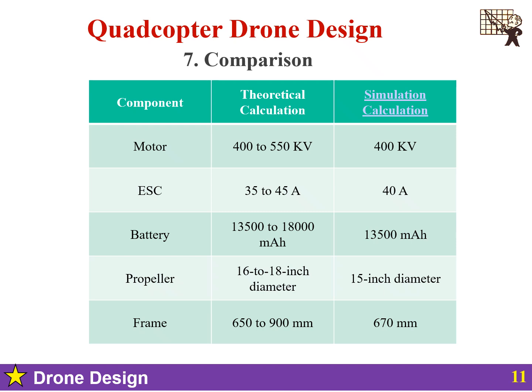ESC ratings. It lies between the range of 35 to 45 amperes in the theoretical calculations, while in simulation we get around 40 amperes. The simulation chooses the mid-range, balancing the cost with thermal margin. This represents professional grade components with adequate headroom.